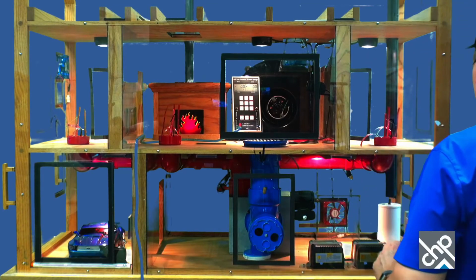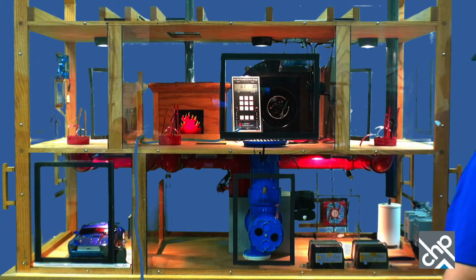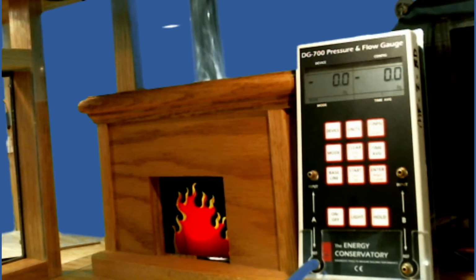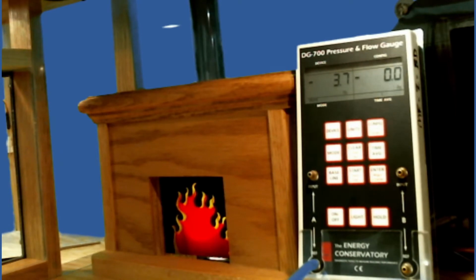So now let's turn that back, fix that. We'll go back to the inside one more time on the living room here. Now smoke's going out. I fixed the return leak, and we're about 0 pressure. So now I'm going to make a change here, and we'll see what happens. Made a big change that time. The house went negative, or the building's sucking. So what kind of leak do we have? Got a supply leak. Supply leaks make the building suck.